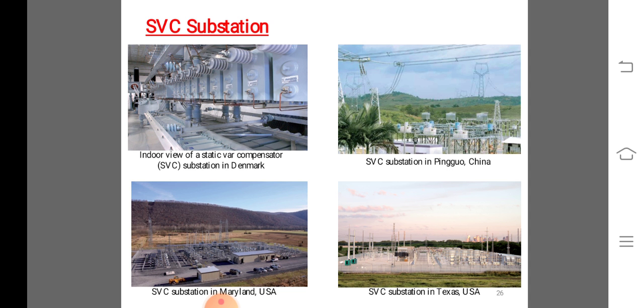Quick control can be exercised within one half cycle just by giving a proper step input to the firing angle control. Static VAR compensators, when installed, reduce the voltage swings at the rolling mills and power system buses in drive system applications. They compensate for the average reactive power requirements and improve power factor.